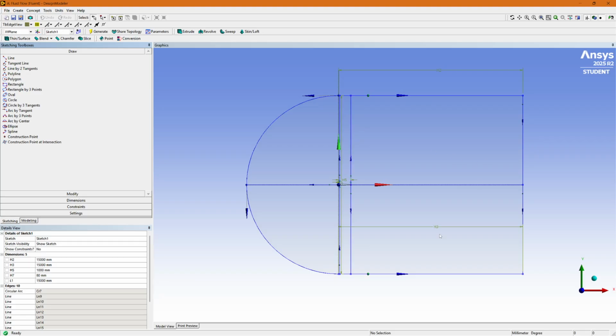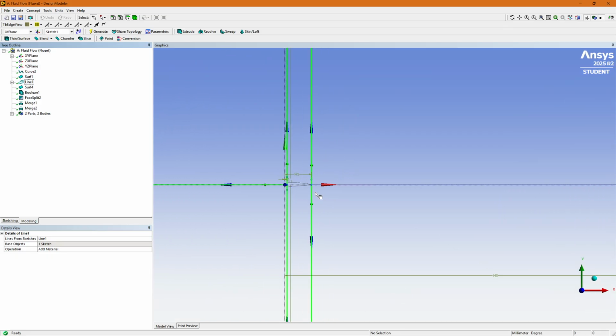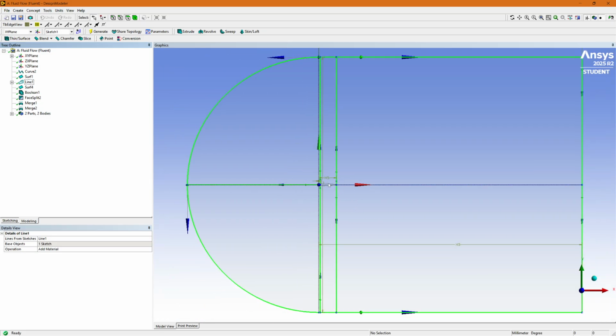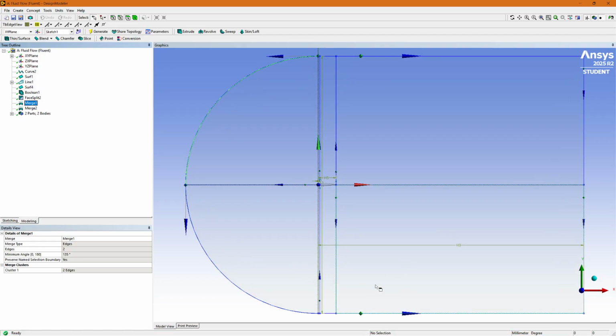And then we also just broke this up into 6 chunks using a face split. That just gives us a little bit more flexibility with creating our mesh. From there, we did a boolean to remove the airfoil from the fluid domain to make it essentially a walled body. And these two merges here are just connecting these points up here in the bottom. For whatever reason, through face splitting, these get disconnected. So just remerging them makes the body solid again.